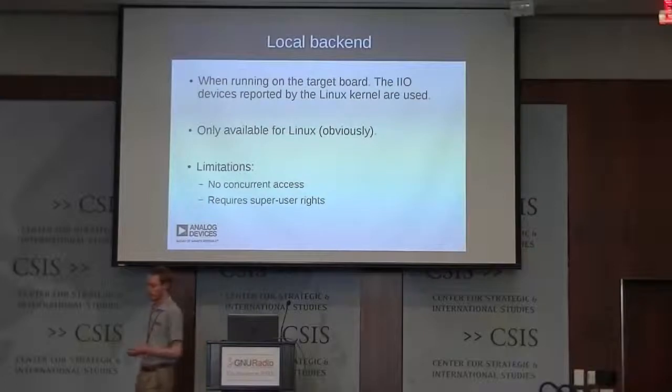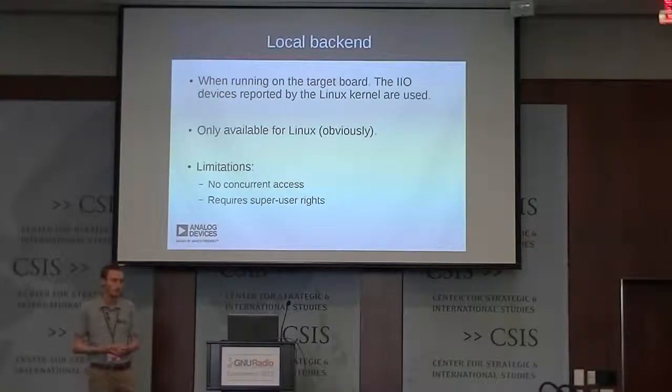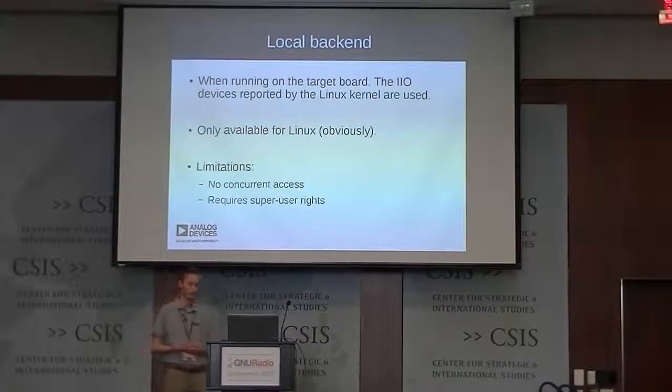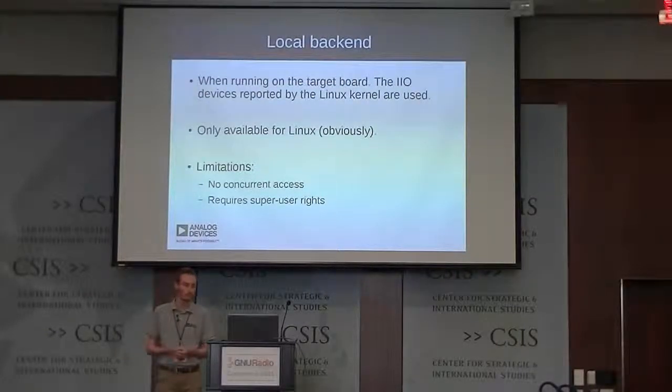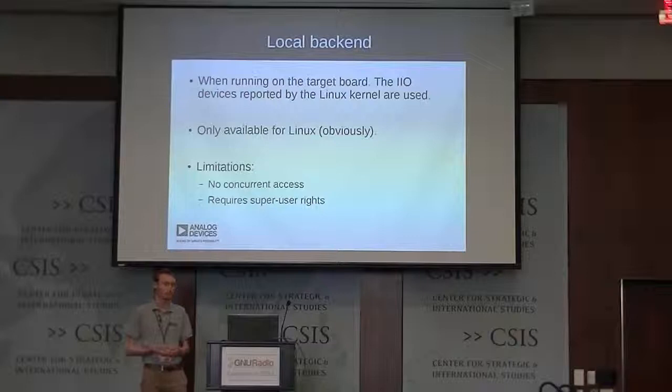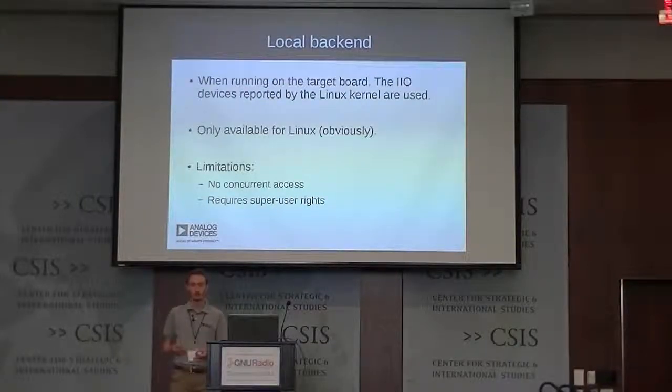So the local backend of the library is to be used when the application will run directly on the target board. So obviously it's only available for Linux because the IIO system is the framework of Linux. It has the same limitations as the kernel. You can't have multiple applications using the same device at the same time. As the sysfs virtual file system and the device nodes are owned by the superuser, you need superuser rights to be able to run your application.